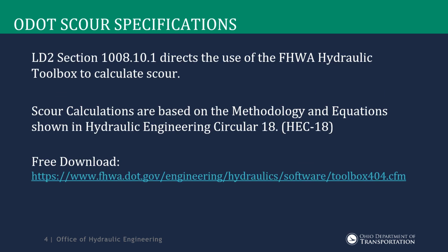If you look at section 1008.10.1, it will direct you to use the FHWA Hydraulic Toolbox to calculate the scour. All of the scour calculations in that software are based off of those shown in Hydraulic Engineering Circular 18, otherwise known as HEC-18.